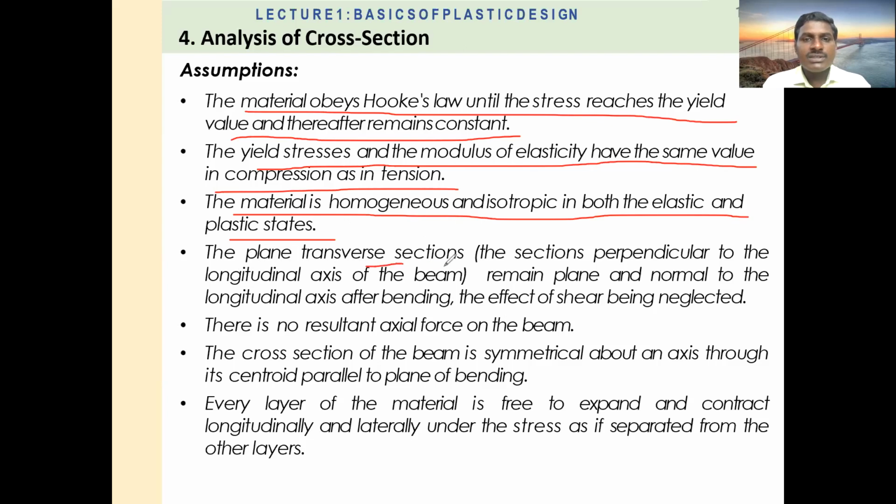Then, the plane transverse section remains plane and normal to the longitudinal axis of bending. As we have seen, your plane of section is transverse and it remains plane and normal to the longitudinal axis after bending. That assumption we have also seen in the analysis of beams in structural mechanics. Then, there is no resultant axial force on the beam. That assumption we have to keep in mind.